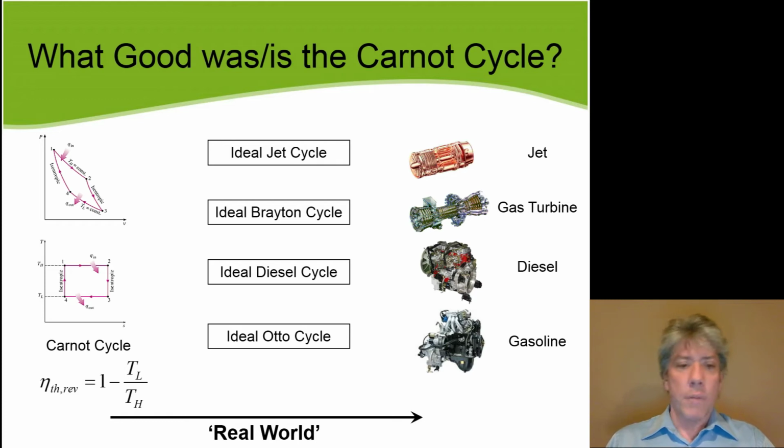Of course, we can never achieve it, but that's kind of like where the bar is set, right? We simply can't go faster than that. So that's the value of the Carnot cycle, and of any reversible cycle really, is primarily what's the best we can ever do with any engine. And of course we know that it depends on the temperature of the source and the sink, and so that actually helps us with all these real engines, because these real engines have similar characteristics to the Carnot cycle in the sense that the higher you make the thermal source for these engines and the lower you make the thermal sink for these engines, typically the more efficiently these engines will operate. So the Carnot cycle is very insightful and very useful, albeit very theoretical.